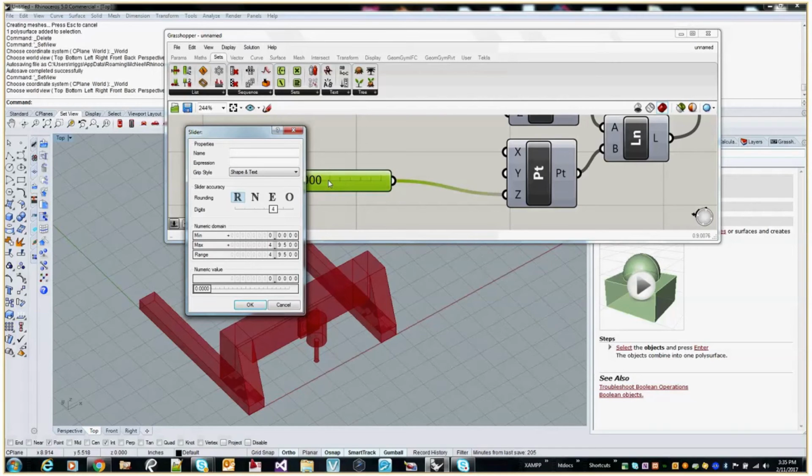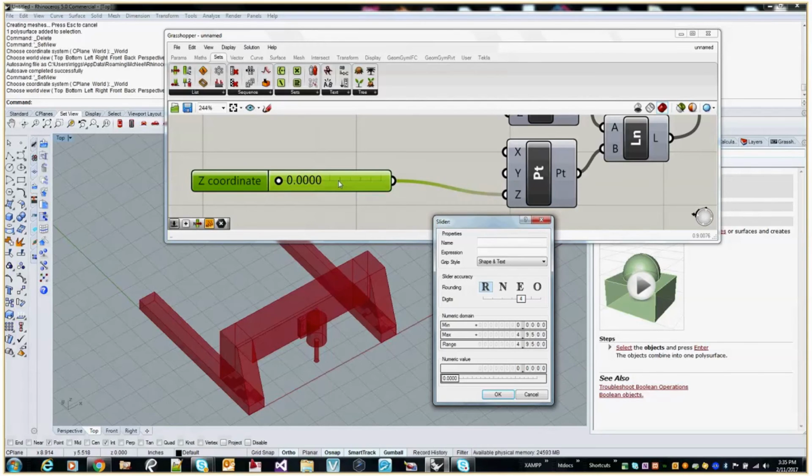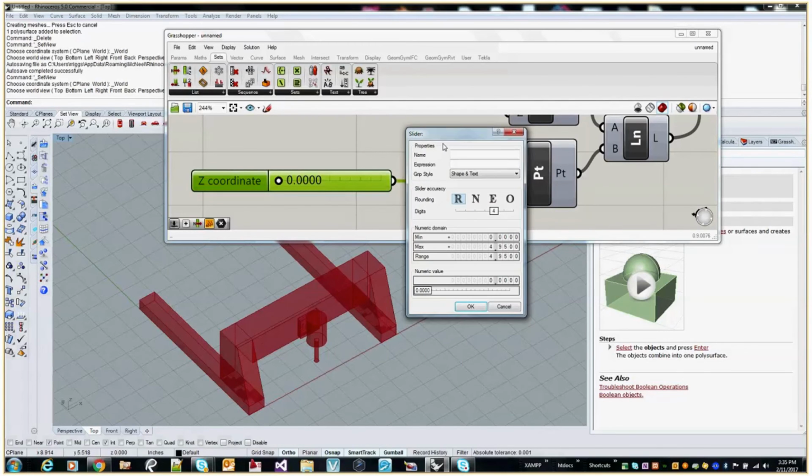But I don't really want to start messing with my understanding of a positive input going in a negative direction. That won't follow G-code. And if you ever had to parse out G-code, you'd have to be certain you multiplied it times that negative value to watch this go down properly. And if you multiplied it in the wrong direction, you're going to keep fighting the limit switch on the home position of the Z-axis. So this is just the easiest way to deal with this, is to set your maximum as being 0 and your minimum as being whatever we want as a minimum.